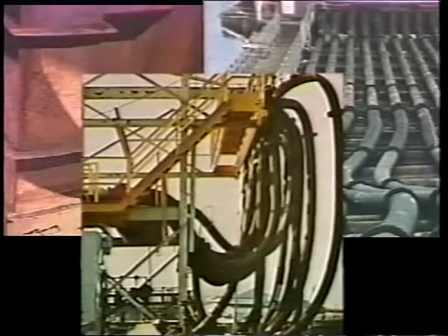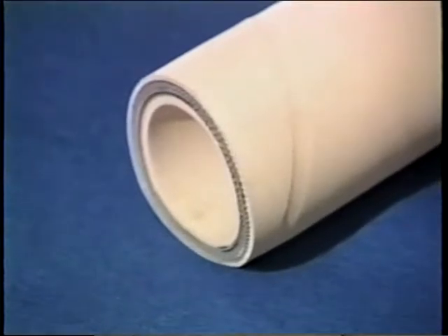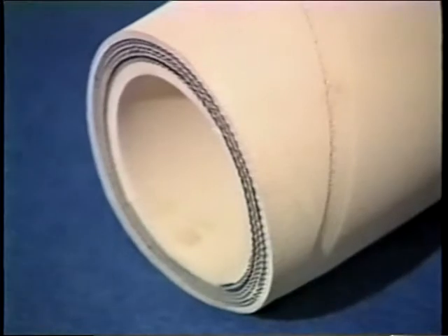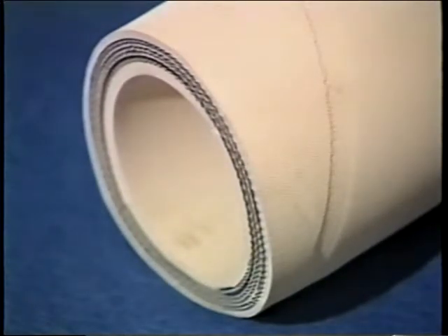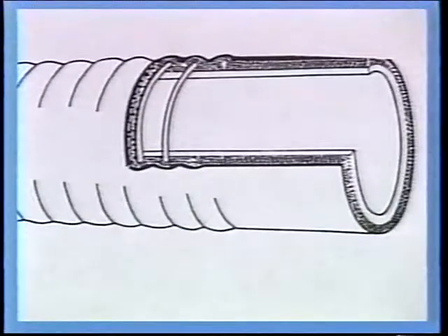Typical applications of hand-built hose are material handling, bulk petroleum, and where the high volume capacity of a large diameter is required. Most hose constructions have plain ends. This is simply an end resulting from a cut through the cross-section of the hose and is the most common end. However, a variety of hose end treatments are available with hand-built hose.